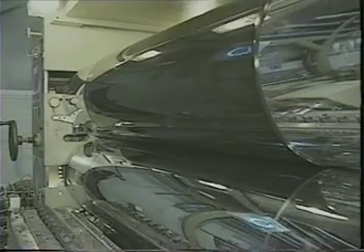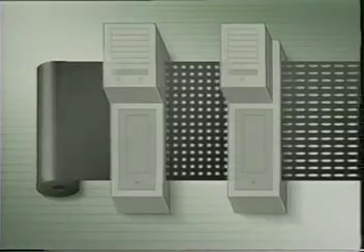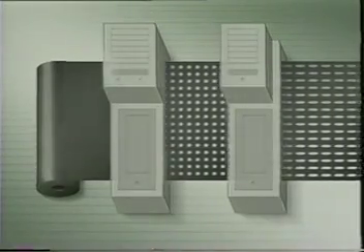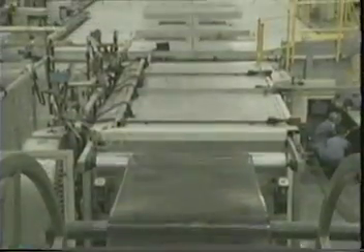High or medium density polyethylene is used to produce punched and drawn geogrids. Drawing or stretching the polymer causes the molecular chains to orient in the direction of drawing. This molecular orientation increases the tensile strength and deformation modulus of the polymer.